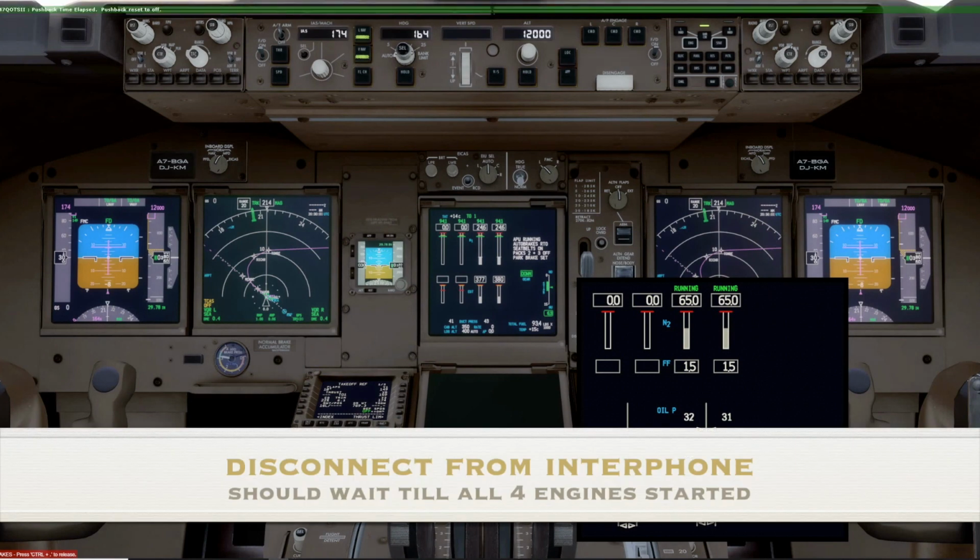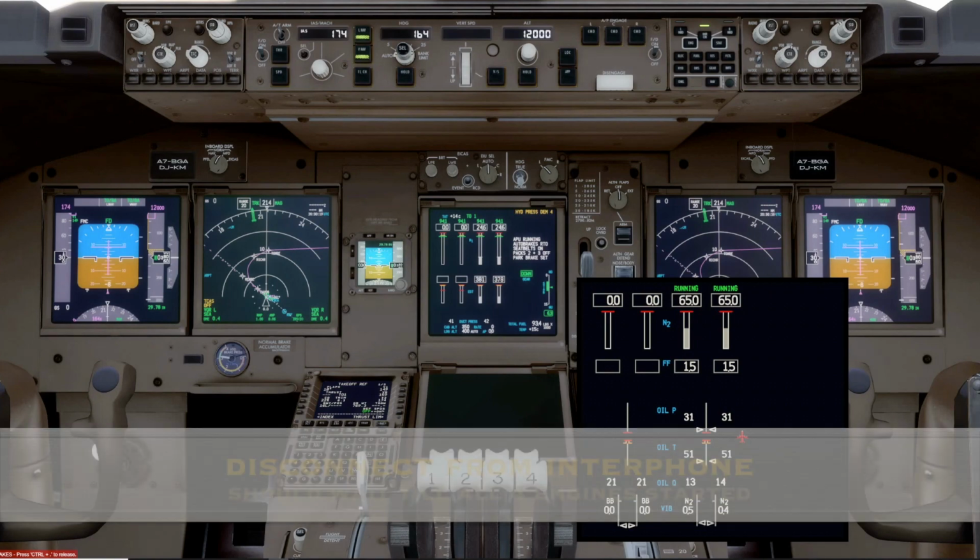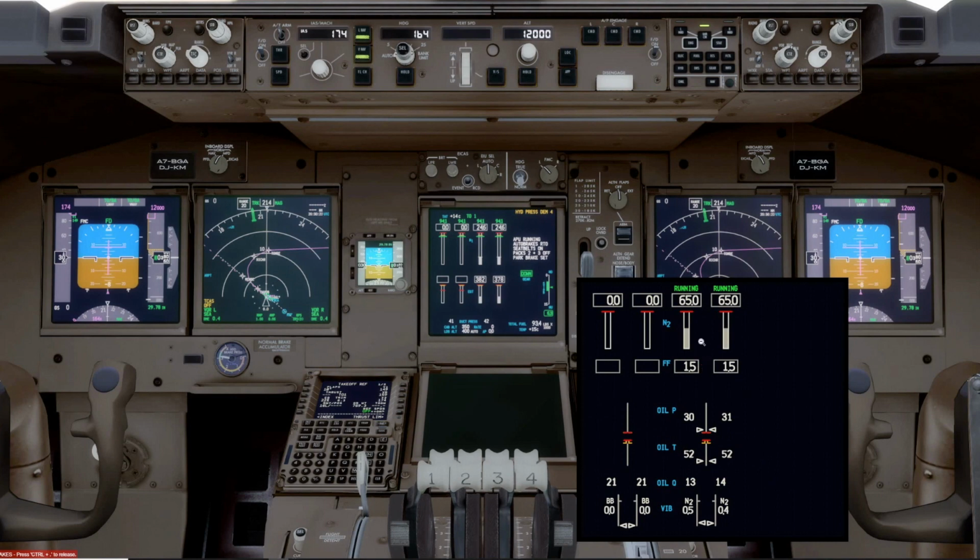And then you'd probably say, go ahead, you're clear disconnect and show me the pin on the left side, verify the nose gear steering is not locked out. And then you'd say, okay, clear disconnect, your steering is not locked out. We'll show you the pin on the left, and have a good flight so long. Notice when 3 and 4 reach the idle target indicator, it went to running, that stays for 30 seconds, then disappears.